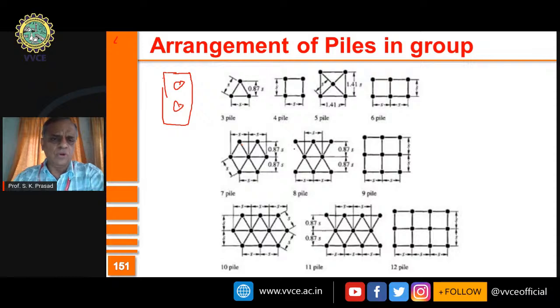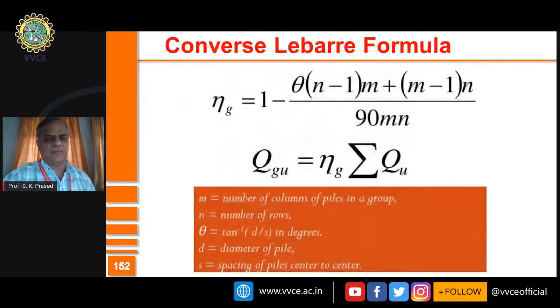Then you're going to put them together, and there will be some specific spacing between them. When the spacing is small, you require more number of piles, but there is a likelihood that they overlap, and hence capacity is reduced. When the spacing between them is very large, then the interaction between the piles is less. They act independently. You need that interaction also. So there is a need for that coordinated effort. So 2 pile, 3 pile, 4, 5, 6, etc. pile systems are given.